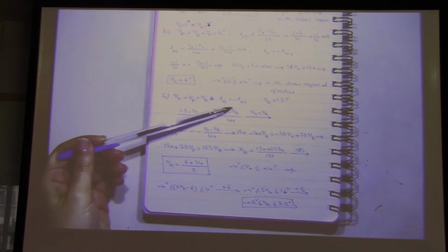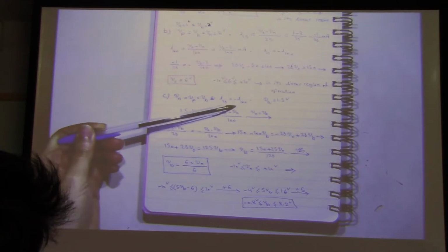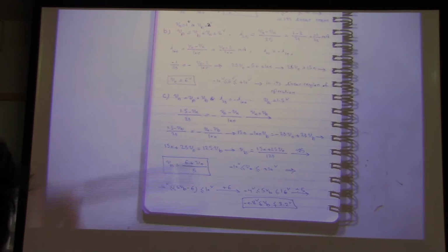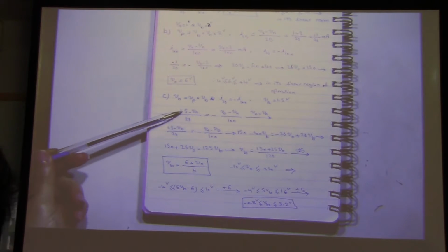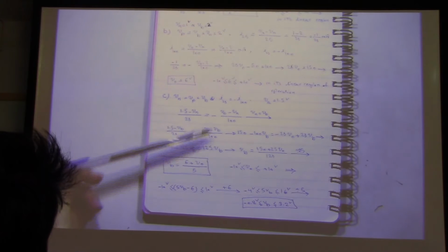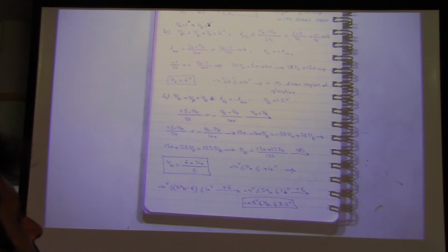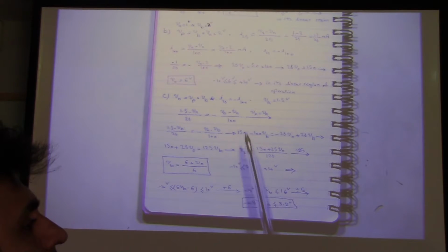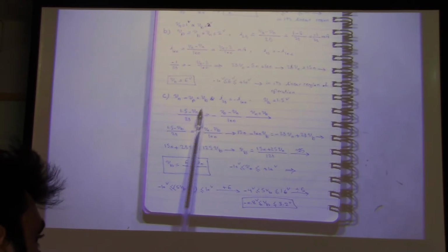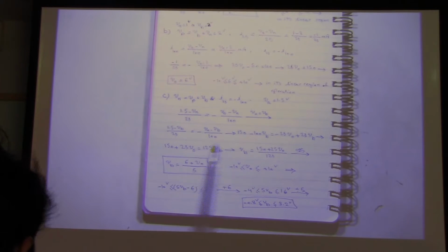So over here, again, the same thing. I-25 is equal to minus I-100, and I hope nobody has problem with this equation. And VA is 1.5. So what is I-25? 1.5 minus Vn over 25 milliamp is equal to minus V out minus Vn over 100 milliamp. Again, here Vn is equal to Vb. So just substitute it here. So 1.5 minus Vb over 25 is equal to this term.